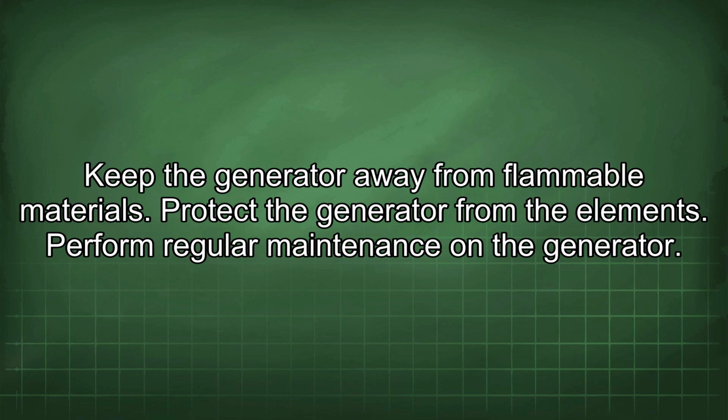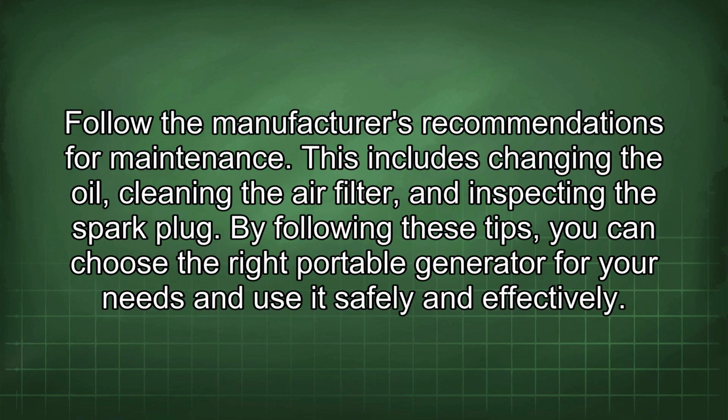Perform regular maintenance on the generator. Follow the manufacturer's recommendations for maintenance. This includes changing the oil, cleaning the air filter, and inspecting the spark plug.